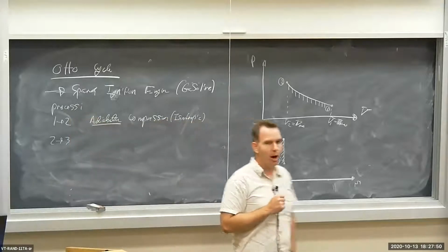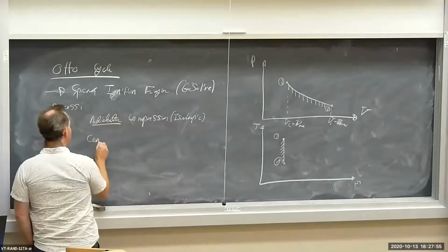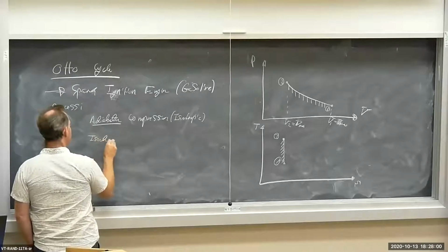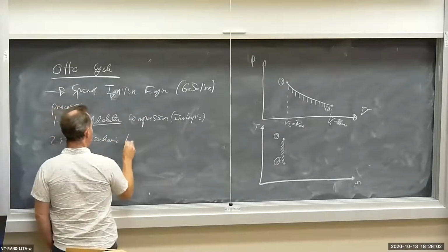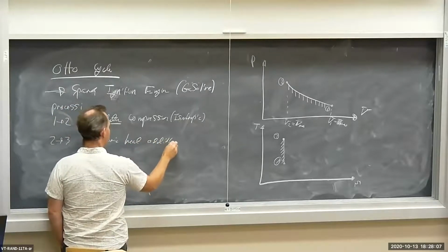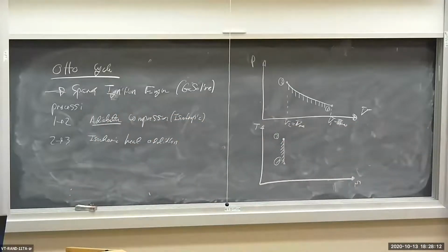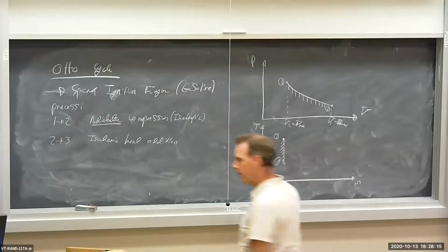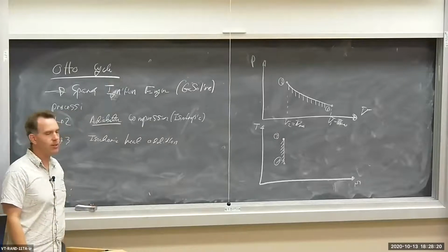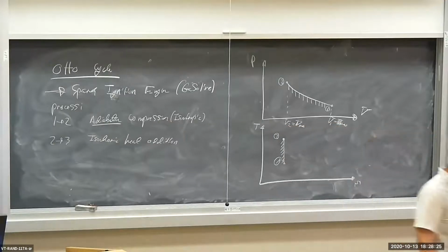That means it's a constant volume heat addition process, or if you like, isochoric heat addition. So a spark occurs inside the piston cylinder device. The fuel burns very quickly. But as far as the piston cylinder device is concerned, the heat is released instantaneously at constant volume.